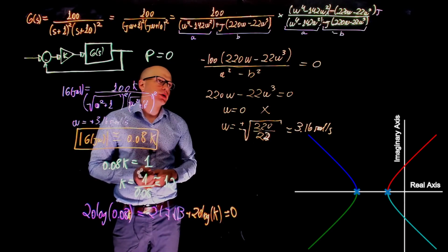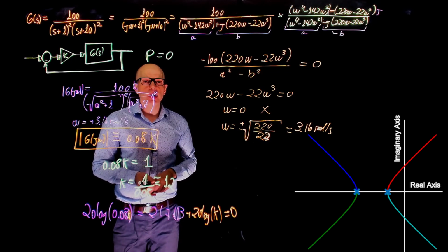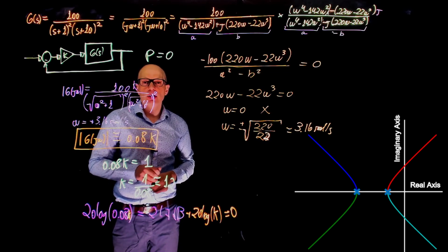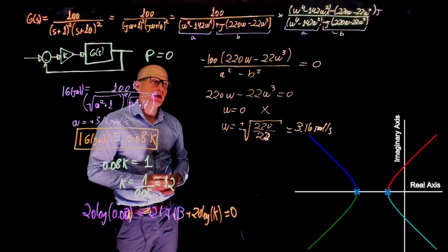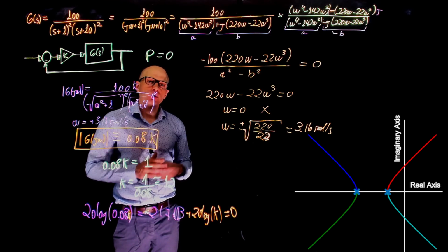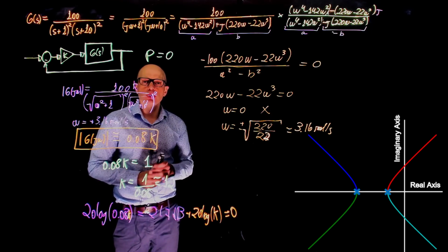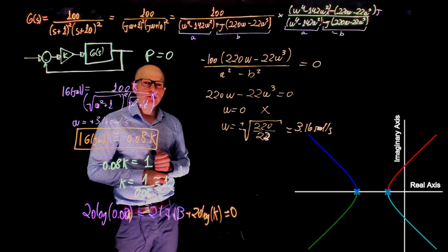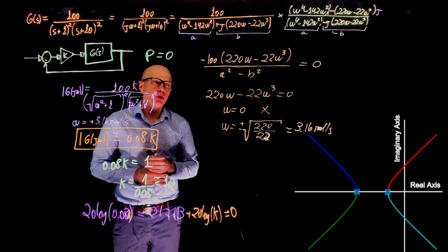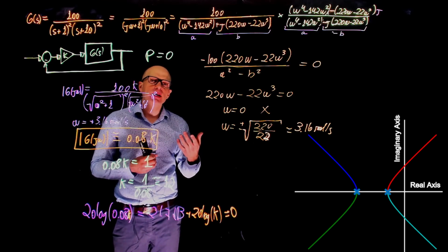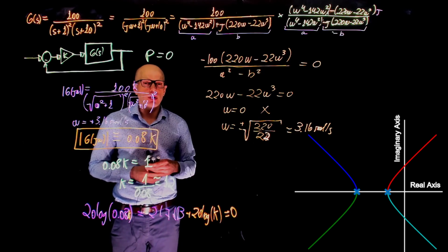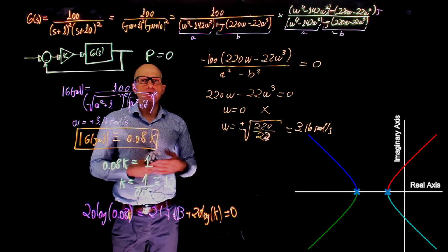Here is the root locus. Looking at the root locus, what can we say? We can clearly observe the same thing. For low values of K, the system has no unstable closed loop poles. Past a given value, the system has two unstable closed loop poles, and that maximum value is exactly 12. We can verify that using the Routh-Hurwitz.